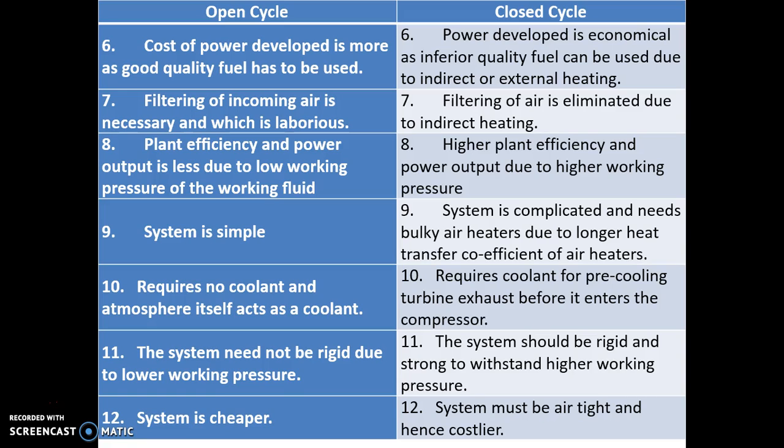And in the open cycle the power developed cost is more, as good quality fuel has to be used. That means how much fuel you are using, that much cost will come. But in the closed cycle the power developed is economical, since we can use fuel of any quality, since it is not directly in contact with the working fluid. And in the open cycle we have to filter the incoming air, and in the closed cycle it is not necessary because we are not taking any air inlet.